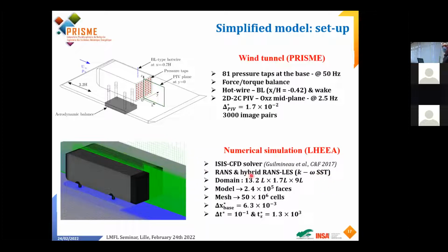And another one, which is a hybrid Reynolds LES. Sometimes it's called DES. Here it's a DDES, for detached eddy simulations. And after, we can find plenty of letters to have all those models inside. So here it will couple the advantages of Reynolds close to the walls and the advantages of LES far away from the wall. Let's say it like this.